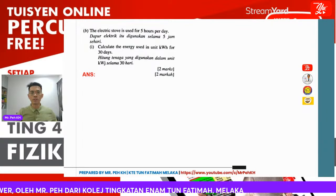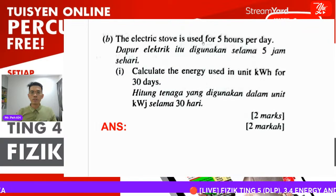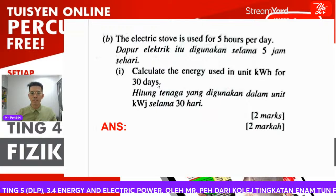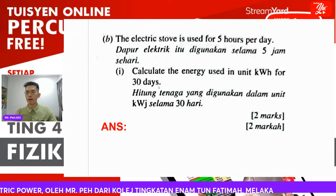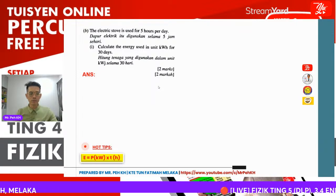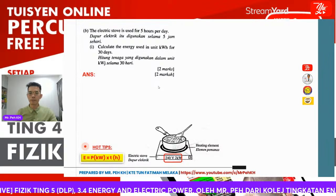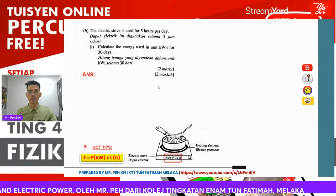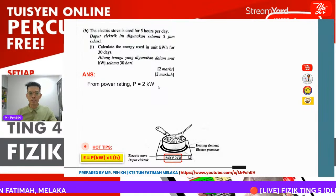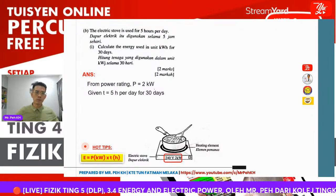Okay, then the next will be a calculation question. The electric stove is used for 5 hours per day. Calculate the energy used in unit kilowatt hour for 30 days. So firstly we need to find kilowatt hour, right? So we need to use the power rating. E equal to Pt, we discussed already, we're using this formula. Just now we also discussed the power rating label, 240 volt, 2 kilowatt. So the power is given by the power rating already, P equivalent to 2 kilowatt. Please maintain in kilowatt as we want to calculate the energy in terms of kilowatt hour. So 5 hours per day for 30 days.